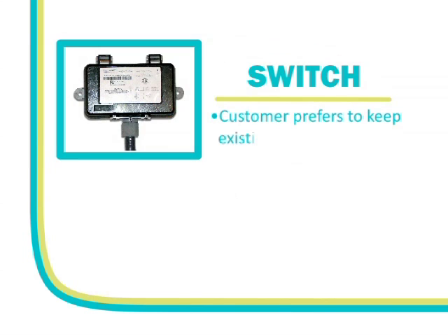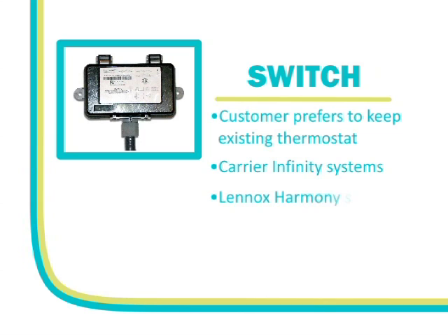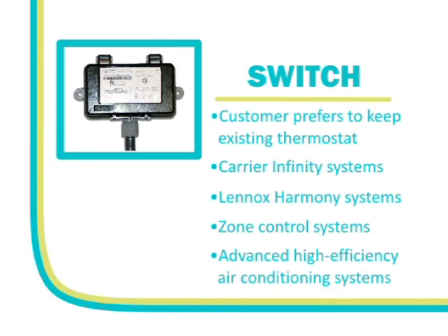Here are a few possible scenarios where it would be appropriate to install a switch rather than the smart thermostat. Customer prefers to keep existing thermostat. Carrier Infinity systems. Lennox Harmony systems. Zone control systems. Advanced high-efficiency air conditioning systems with communicating thermostats.